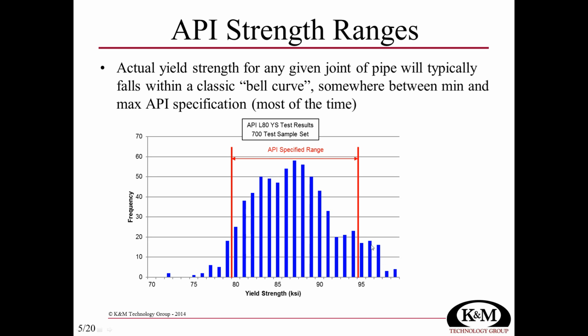So it's really important, when you're thinking about what you're doing to the pipe, to consider just how strong the pipe is and how confident we are of its strength. What this graph tells me is that any given pipe can have a pretty wide range of strength. Just because we look into API RP 7G or we look into THL's DS-1 catalog and look up the strength of the pipe, know that what's going into that is this line right here. When we're talking about the strength of the material, we're assuming that the pipe is this line. Well, it's probably stronger than that, but we have to assume something. So we assume that the minimum strength is along this line.